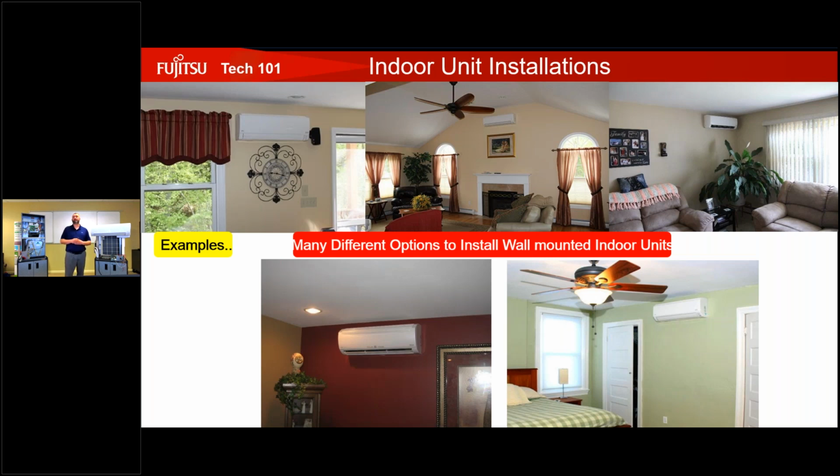On the top middle photo, this could be one of those scenarios where we want to put a wall-mounted thermostat with this unit, because the temperature up here could be 3, 4, 5 degrees warmer than the temperature down here, which could lead to an uncomfortable environment because we're testing the temperature at the indoor unit, which is much higher.